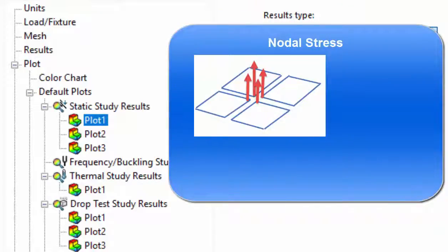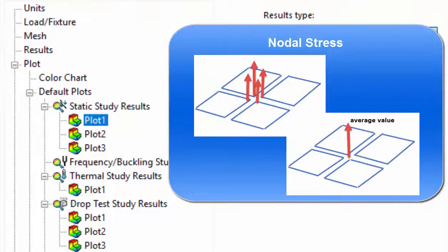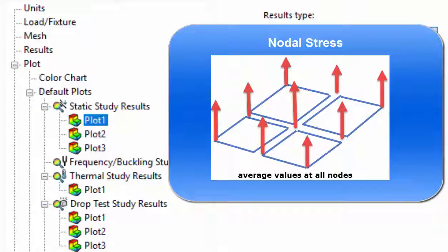This will take all stresses calculated at each node and average them. Remember that each element connected to that node will be contributing, and hence they're all averaged. We won't be able to see any stress jumps across adjacent elements using contour plots. Mesh section is the only way to do that, and we will cover that in a later video.